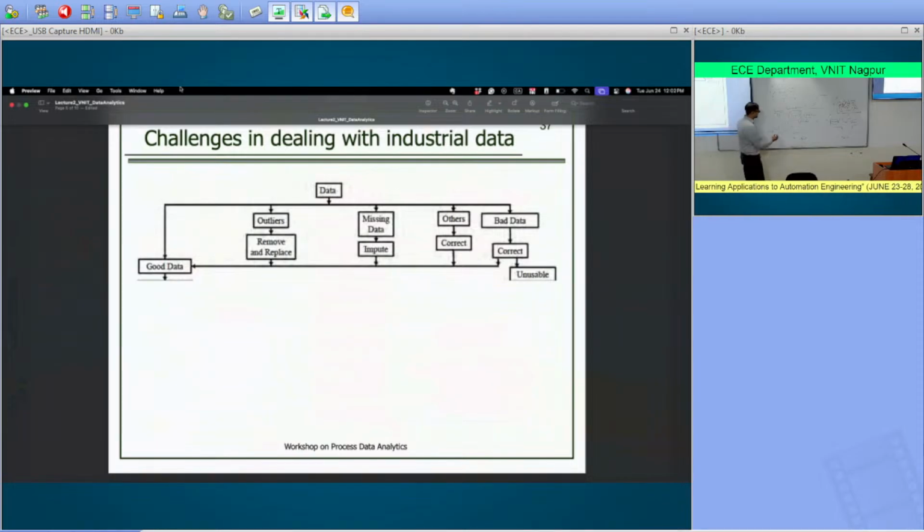You can, for instance, check if there is a valve here, and say there is a flow meter here. You're measuring the flow rates. Let's say you don't see any abnormality here, you haven't changed this, but your level transmitter shows this, right? Then you know that these are not the real measurements from your level sensor, because it's just physically not possible for your level to have gone down like that and come back up while you've not made any changes to the inlet flow rate or to the exit flow rate. Right? So those are outliers. So we want to find those outliers that don't represent the true behavior of your system.